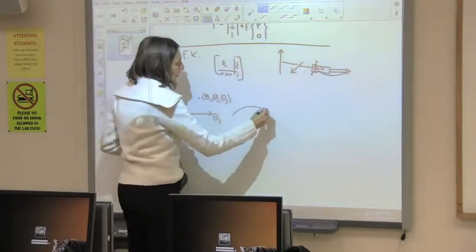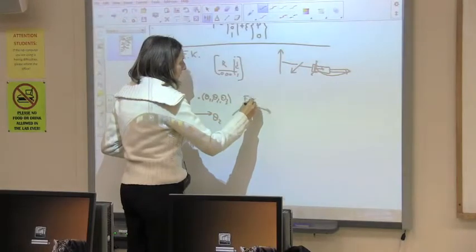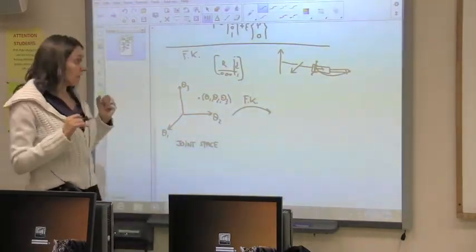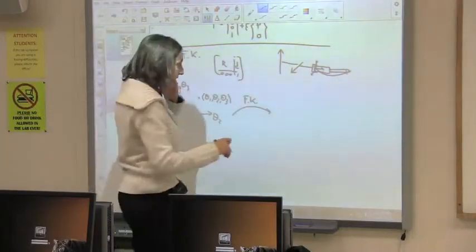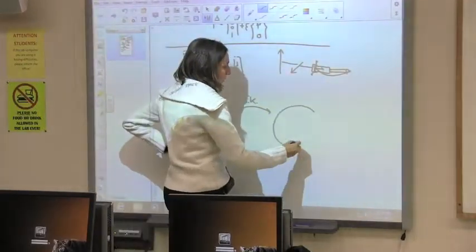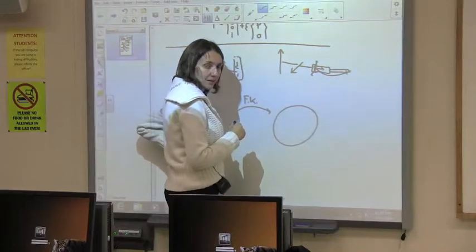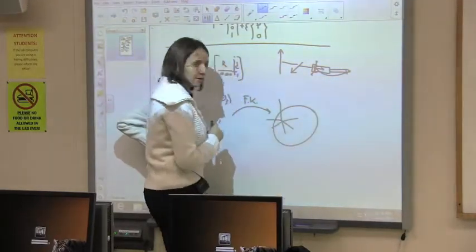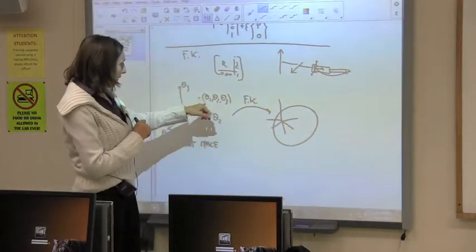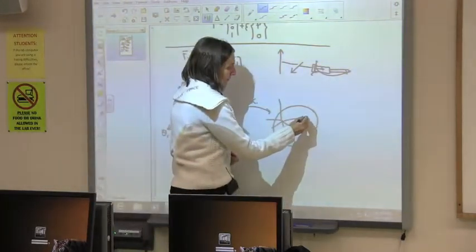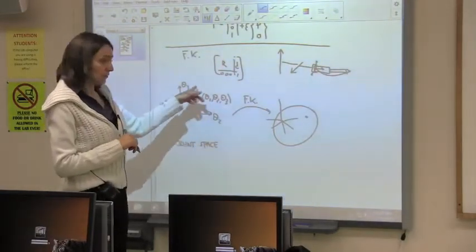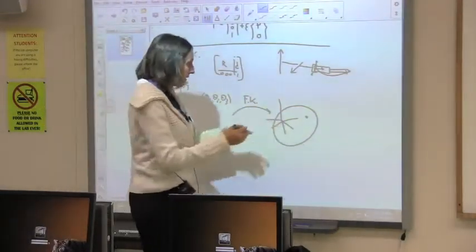And then you do forward kinematics, and then you live in the space of your displacements. When we are doing dual quaternions, this is a quadric in a 6-dimensional space, okay? 1, 2, 3, 4, 5, 6. So you put values here, you get a point here in the quadric. You get a displacement. For each set of values here, you get a different displacement.